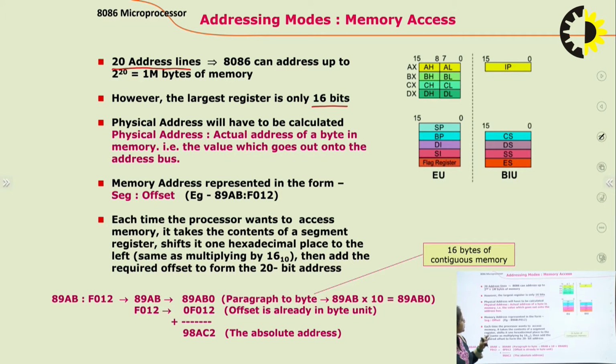For this purpose, the whole memory is divided into various segments, and at a time 4 segments are used, called code, stack, data and extra segment. Each segment register has its specified offset or index registers, and we write it in the form of segment register and offset, like CS:IP. This is the way we write a segment offset pair.